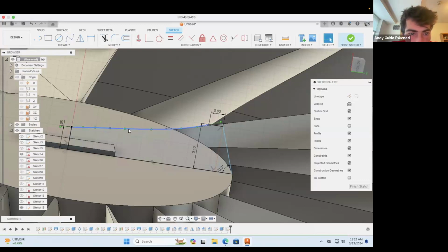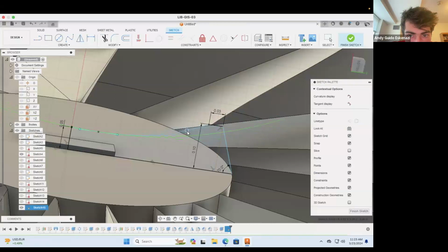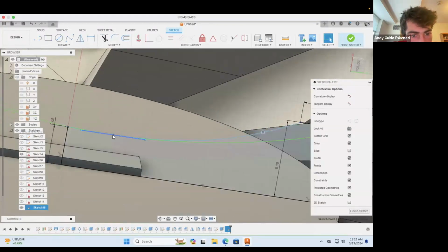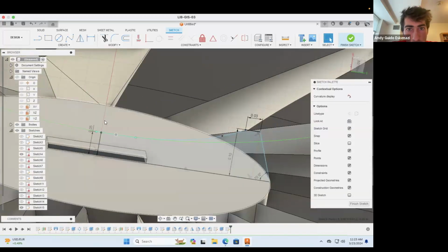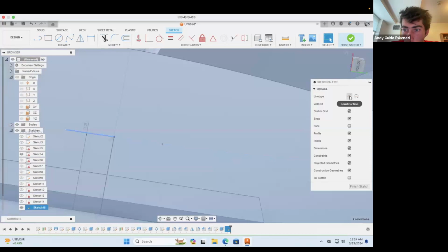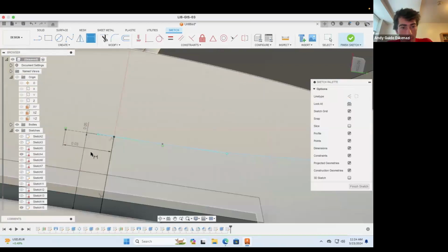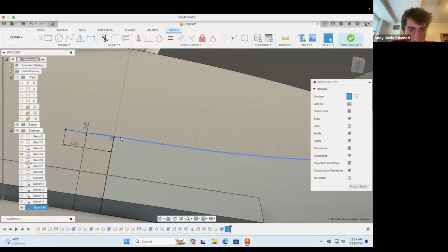I just want to now modify this little spline. Oh, it's this point. If I wanted to be very, very precise, I believe there's the tangent command. What I could do is draw one line that goes like that. It's just a random line that you can make into a construction. There we go. Just define this. And then I can click this line, control click that line, and make those tangent. That way it's completely flat in there.